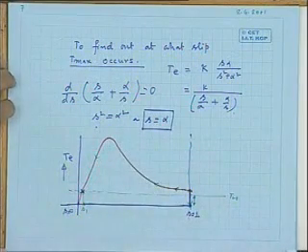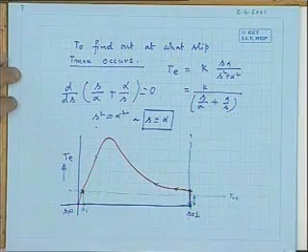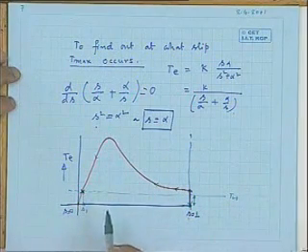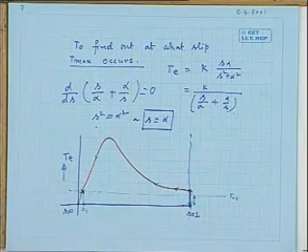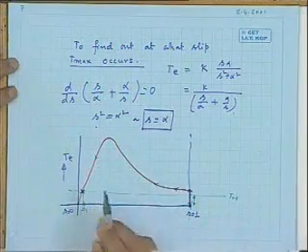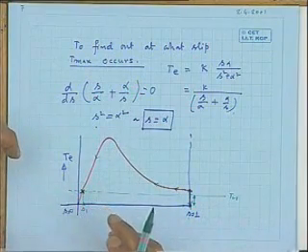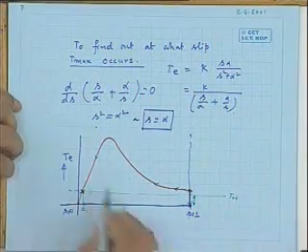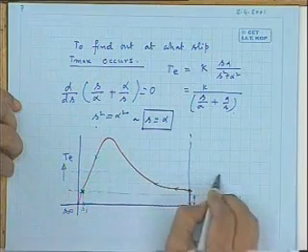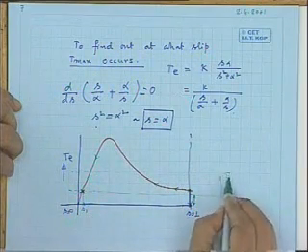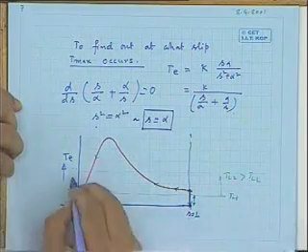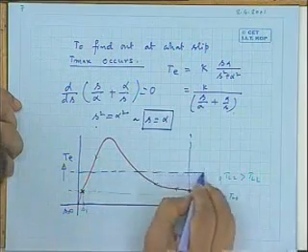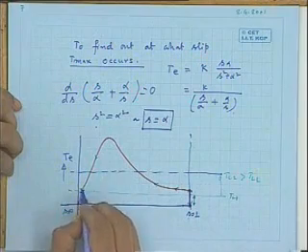Are you getting it? So many things you can now explain with the help of this torque-slip characteristic. So the machine will be operating here. Now suppose I have increased the load torque on the shaft of the machine. It was TL1. The machine started and settled here. Now suppose I have increased the load torque on the shaft of the machine. So how much is the load torque now? Suppose I have made it like this, TL2. Load torque is increased to TL2. TL2 is greater than TL1.